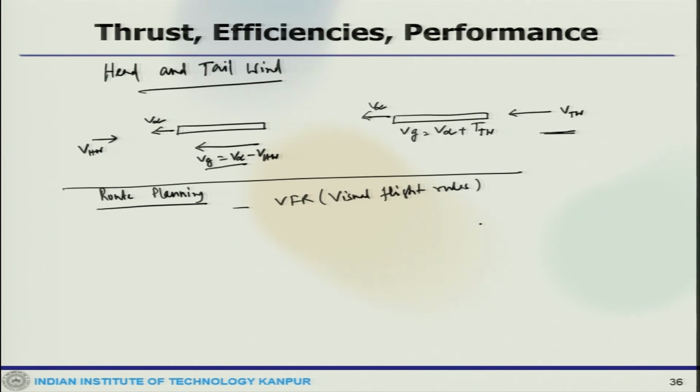The pilot usually chooses a route taking care to avoid controlled airspace that is not permitted for the flight, like restricted areas, danger areas and so on, and the chosen route is plotted on the map and the lines drawn are called the track. During flight planning, 2 points are to be taken into consideration. One is the point of no return, second is the critical point.